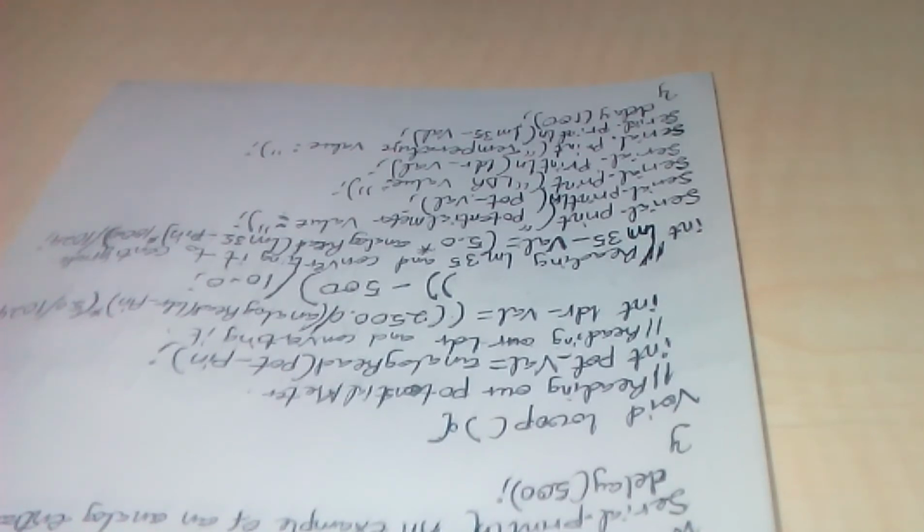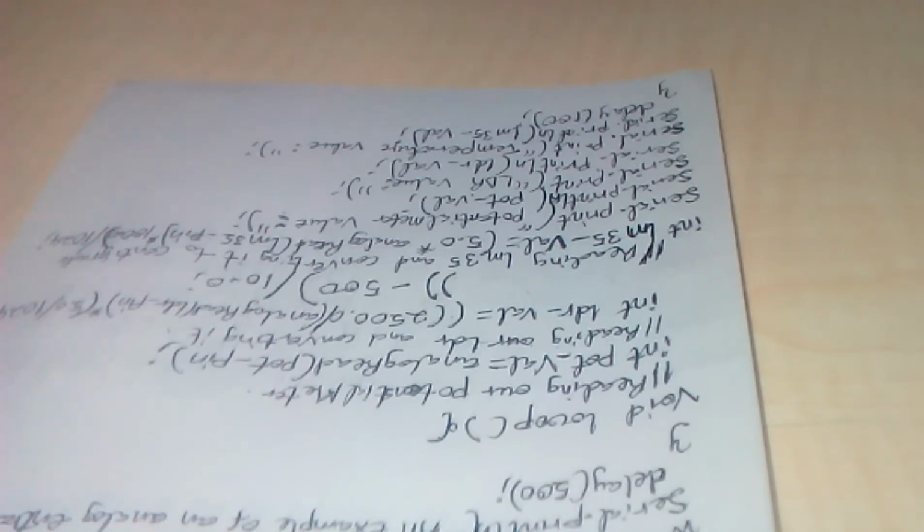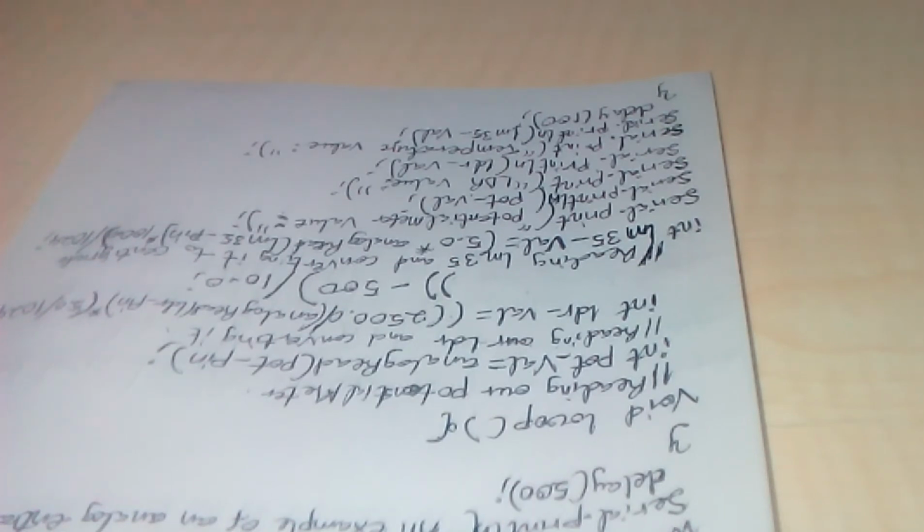It also takes the light dependent resistance, the sensor reads it and converts it into digital for our computer to be able to display it on our serial monitor. With this, we can actually see the value it has converted from our analog to our digital, from our analog to digital converter, ADC.